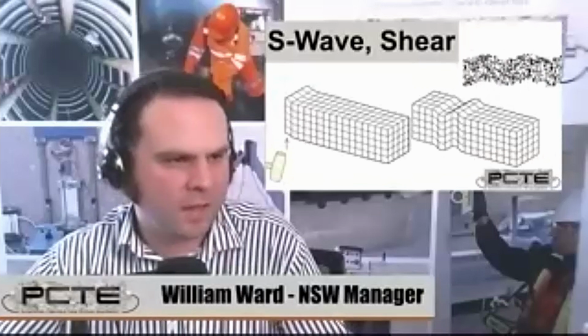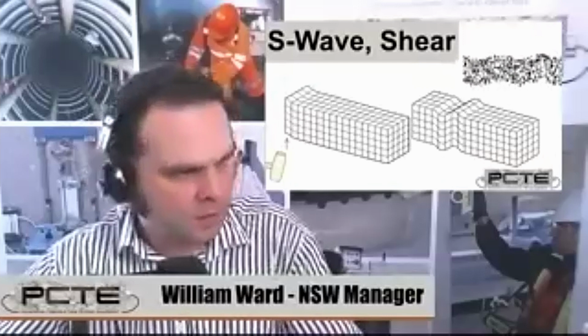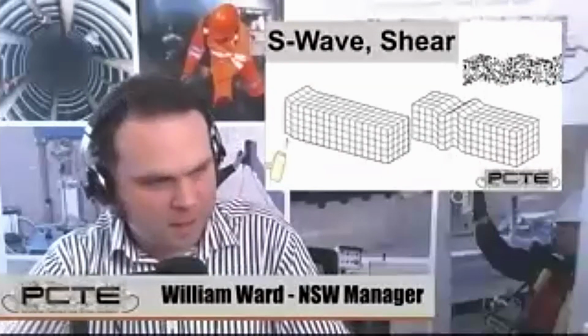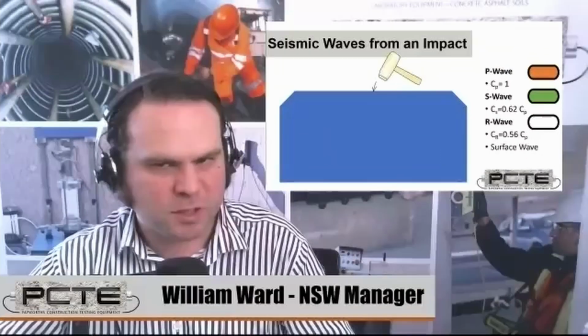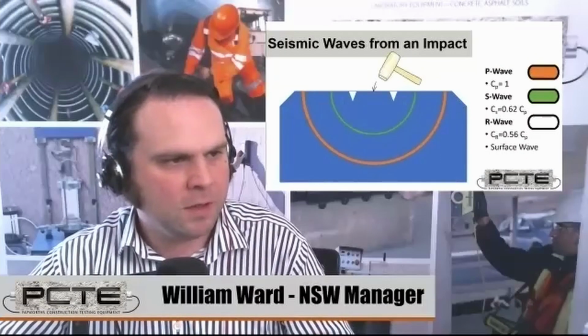The other commonly used energy is a shear wave, where the surface of a material will be moved side to side and the wave propagates as an up and down motion of the particles of that material. Shear wave energy is commonly used in techniques such as ultrasonic pulse echo testing. It's also possible with ultrasonic pulse velocity instruments to have compression wave transducers or shear wave transducers. And there's a difference in the sensitivities and the propagation speeds of these different forms of energy.